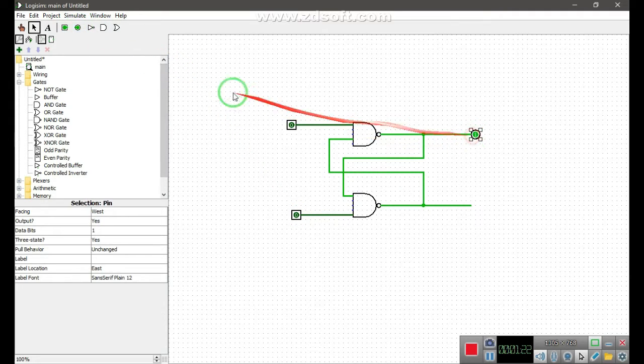Again, NAND gate principles. Okay, and if the reset input R changes state and goes high to logic level 1 with S remaining high, also at logic level 1, NAND gate Y's input R now equals 1 and B equals 0.